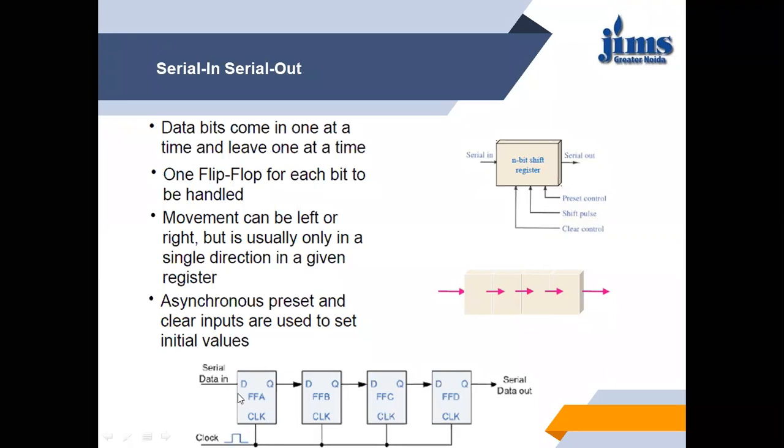When we discussed flip-flops, we put the clock here. For simplicity, I have just put it on the lower line of the rectangle. So here it is clock. Whenever clock is active, all flip-flops will behave according to the input to the flip-flop. The property of the D flip-flop is that whatever the input is, whenever clock is active, that will be reflected at the output. If the clock is 0, then the previous value will be stored in the D flip-flop.